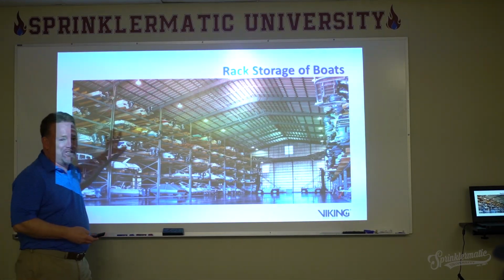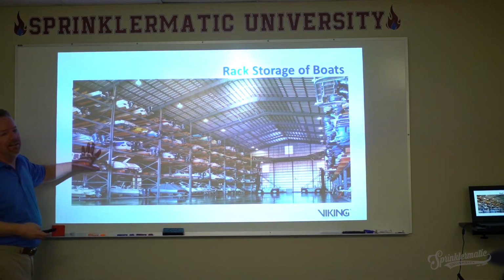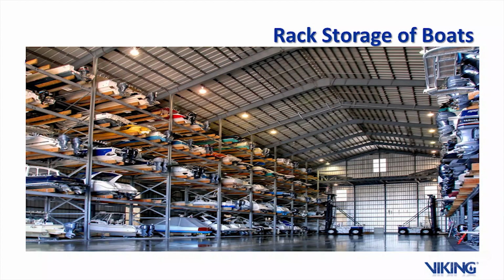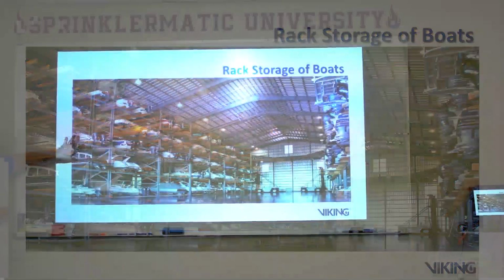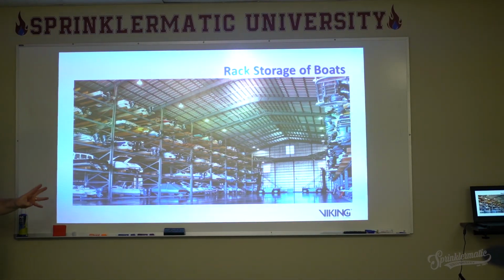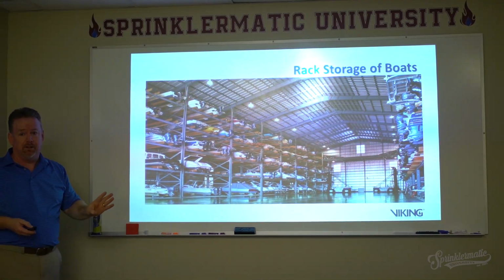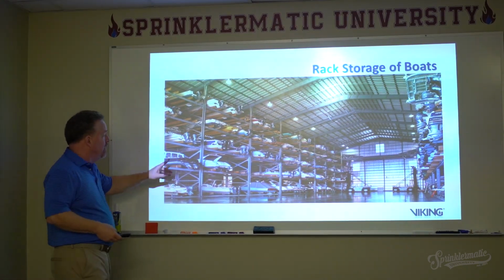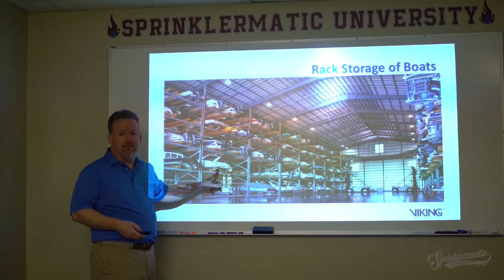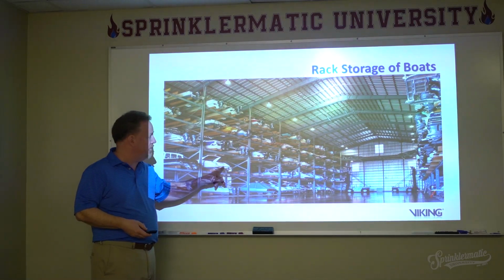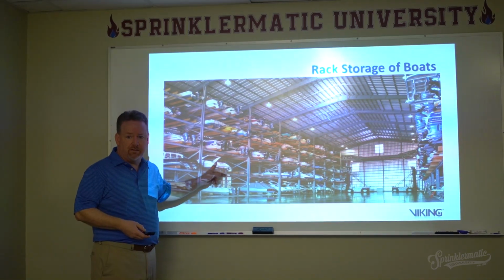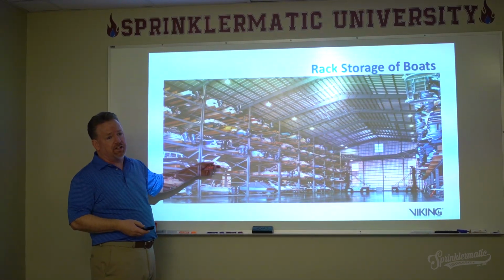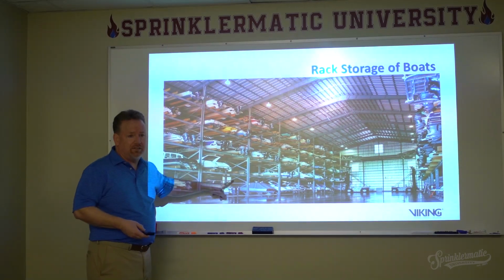Okay, here's something you see down here, huh? Maybe, for a while anyway, you'll see them. It's like, how do we protect them? Here's one with a sprinkler system in it. Okay, this is a big challenge. But once again, the technical committee has punted on this one. We have absolutely no idea what to do with boat storage. And here's the reason why. We can tell you that it's plastic. Okay, great. We know how plastic burns. We know how the foam plastic burns with the seating inside of it. We know that there's fuel in there, so that's going to be a problem. We know that it's in racks.